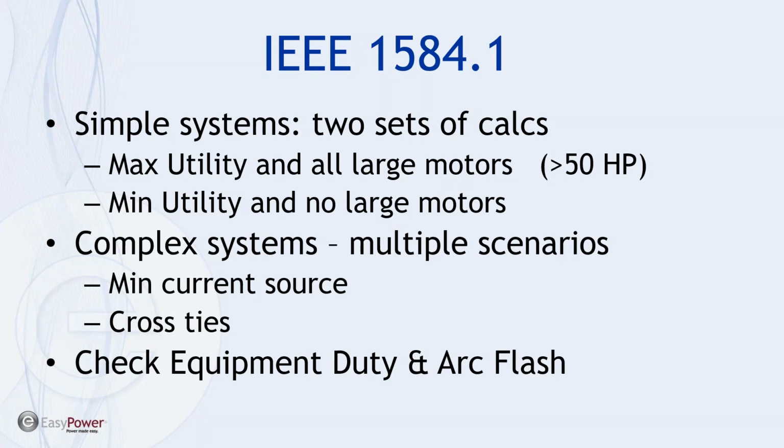And the reason that I asked the one question as I did is that when we're calculating arc flash and worried about labeling, the criteria there is any bus that needs to be opened up and worked on while it's hot are those that require the arc flash labeling and calculations.